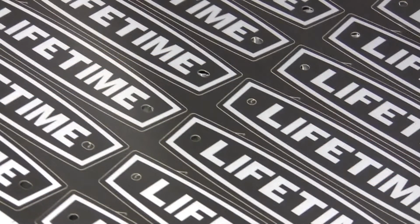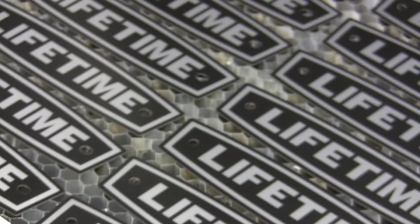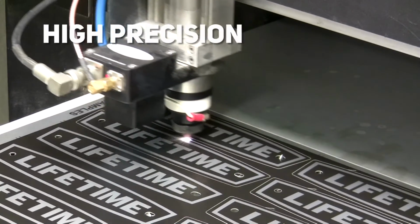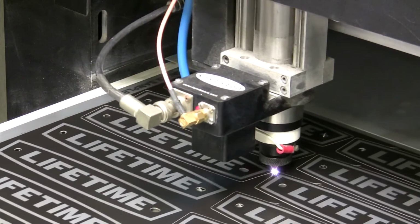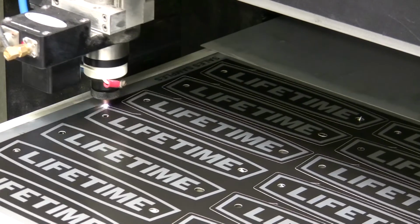Laser cutting leaves clean edges with a high-quality surface finish, making it a seemingly more streamlined process than mechanical alternatives, which often require post-machining treatments. Like milling, lasers are known for precision and accuracy, with some capable of tolerances within 1/1000th of an inch or 25/1000ths of a millimeter. This degree of precision makes laser cutting more costly than punching.